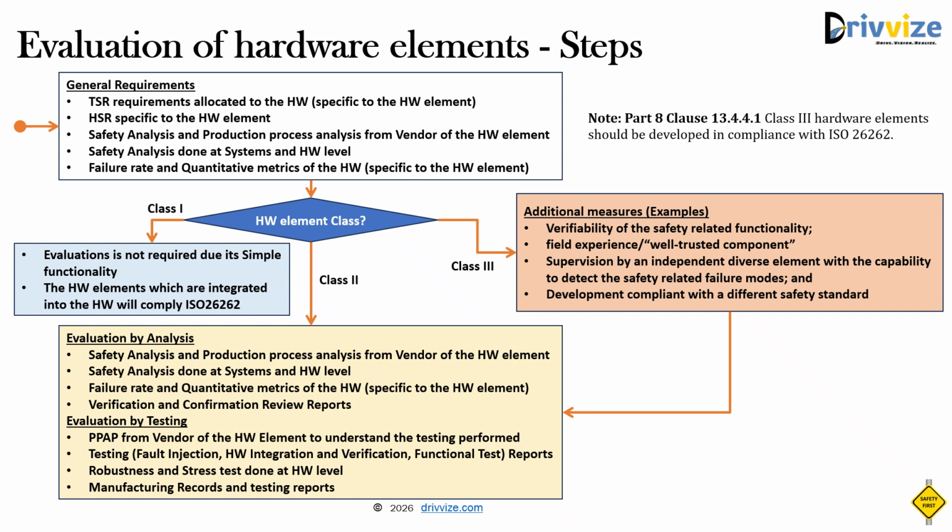Once we have all these inputs, we can start the qualification process based on the hardware class we have already identified. For Class 1 components, ISO 26262 does not require a separate evaluation. This is because when we develop the hardware board according to ISO 26262, the normal testing and analysis activities are already sufficient to ensure the correct functioning of the Class 1 components. For Class 2 and Class 3 components, evaluation is required.